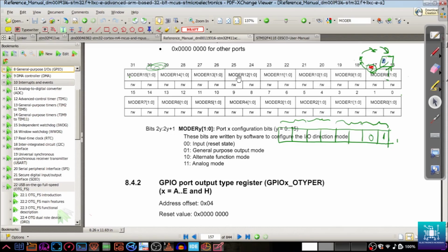So there is a 0, 1 here to make it an output port. For us, say this is the default state where we have the output set for the blue LED. We are just zeroing out the whole thing and then moving 0 1 here, then 0 1 here, 0 1 here. It just keeps moving like this, and the toggle LED basically outputs all ones.